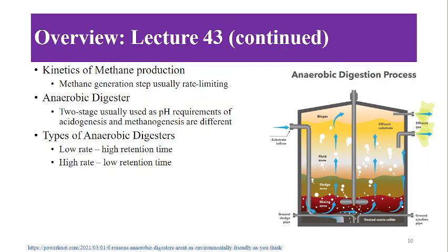Next discussed was the anaerobic digester, in which different zones are present. Here we see first there is a mixing zone, and then we get a sludge zone because of the anaerobic action. Then there is a fluid zone because sludge usually settles down, and then the biogas which is emitted because of the anaerobic action is going upwards, and you get the effluent from here.